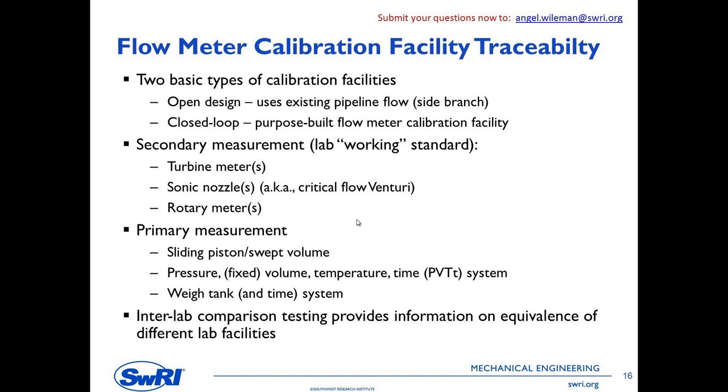The great thing about all these calibration facilities around the world is most all facilities participate in interlab comparisons. So that kind of establishes the equivalence of different test facilities so that you can go to any of these facilities and you should be able to get a calibration of your meter that's within the facility's uncertainty statement. And that's important too because you're not always going to go to the same calibration facility for all of your meters, and the people that you're trading gas with are not going to go to the same calibration facility necessarily as you do. So it's good to understand that these facilities have done testing and continue to do testing to make sure they're essentially all the same.